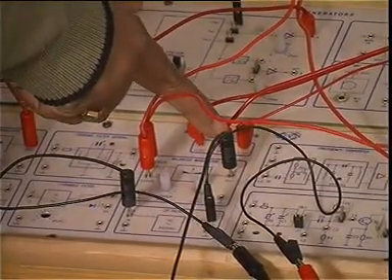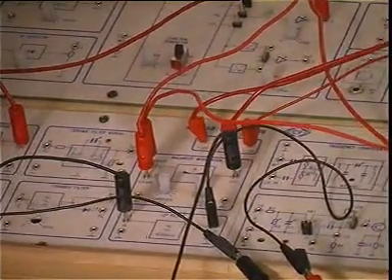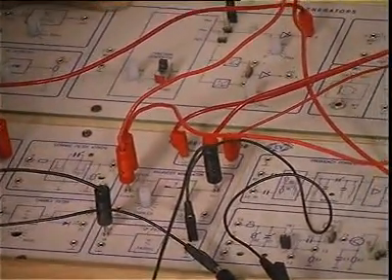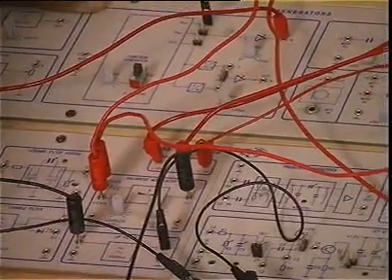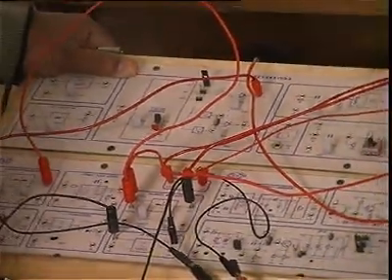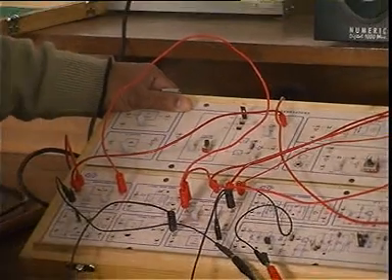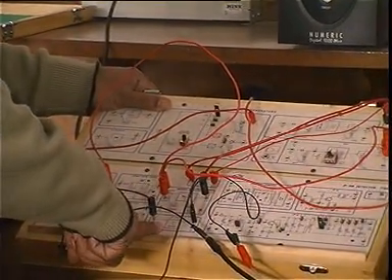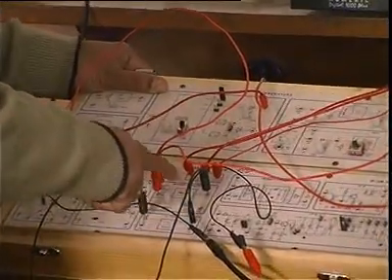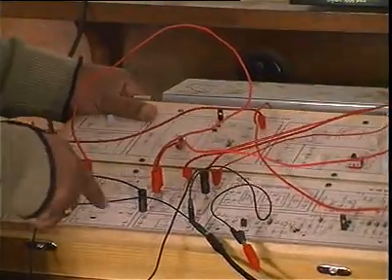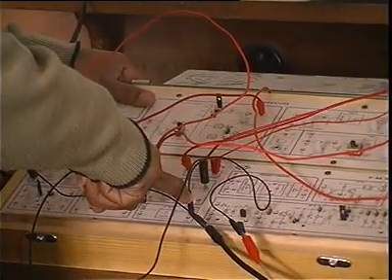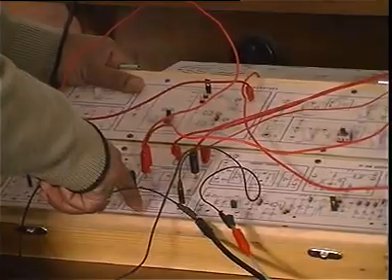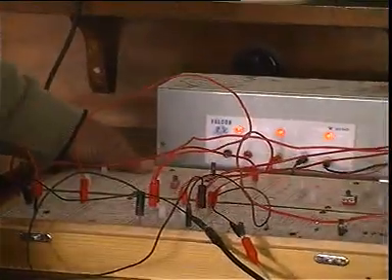If you have a modulated signal, you multiply it with another cos omega_c t term. So you have a cos squared omega_c t term, which you can write in terms of 1 plus cos 2 omega_c t. The 2 omega_c is a higher frequency component. I filter that out using a low pass filter, giving me only the message signal. So at the output I must have the message signal available. Ideally you should be able to recover the message signal, but in this circuit there is some problem with the circuitry inside, and these are the practical problems you will face.